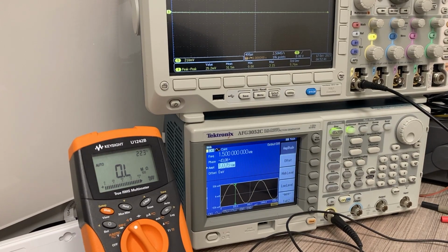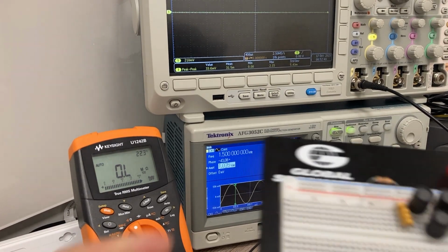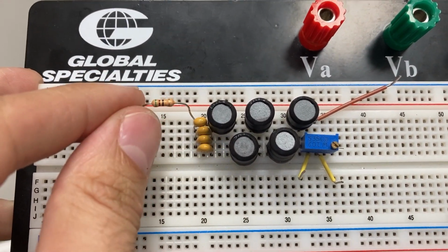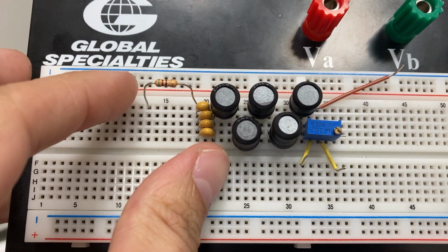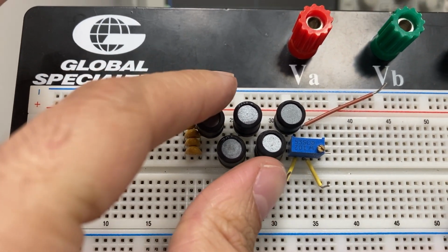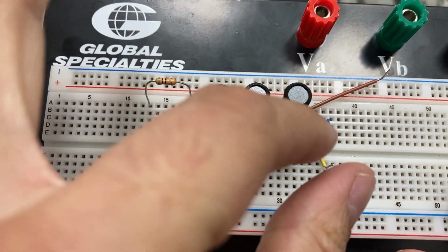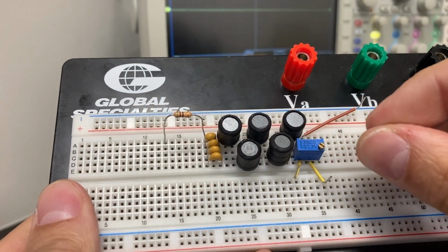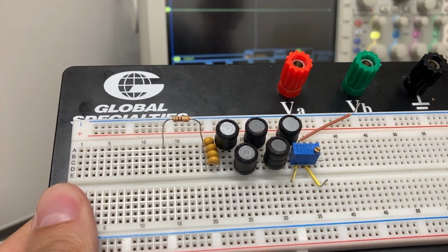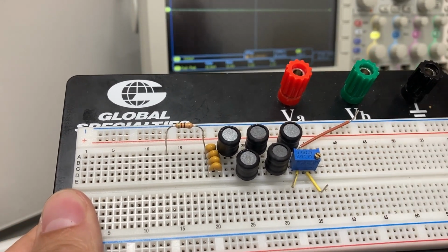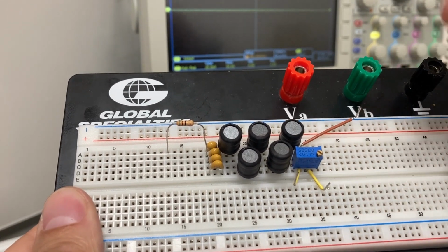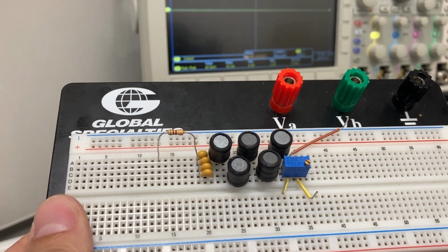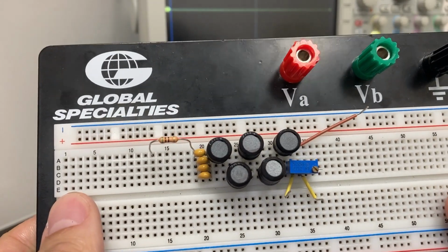Okay, so we're on the experimental portion for this lab, and let me explain my circuit here. These two elements combined, this resistor and this capacitor, compose my Z Thevenin. And this series of inductors and this potentiometer compose my load, right? And I chose a potentiometer because I can vary the value and then get a reading. Now you can just take, if you want, 15 different resistor values and just put them in one at a time, and measure the current through. That actually might be easier in some cases, so feel free to do that.